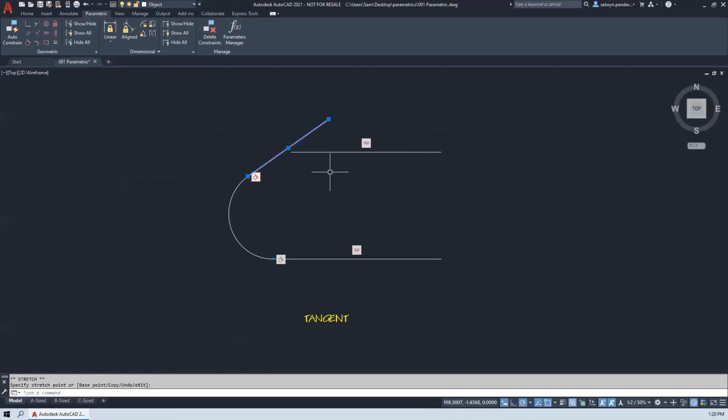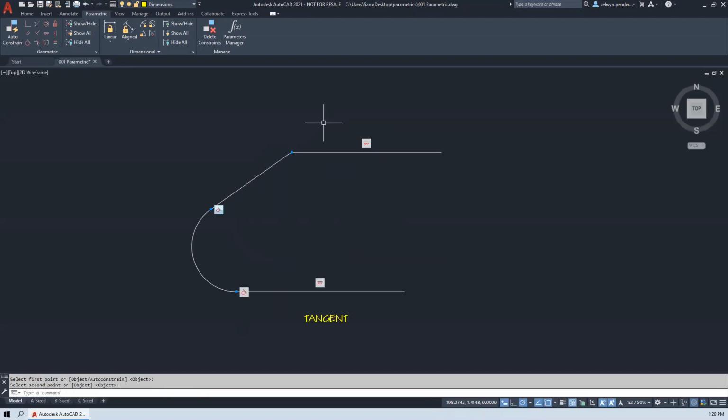Okay, and now I'm just going to put this point onto here. So coincident again, pick near the end of the line. There's only a few snaps when we're applying a geometric constraint to our drawing. You'll see you've got the end point, midpoint, and the other end point. So if I hover over this one, I've got end point, midpoint, and end point. I want to keep this line where it is, so I'll choose that point there, and I want that point to snap.